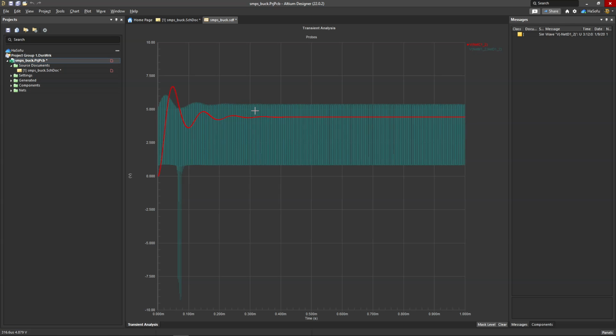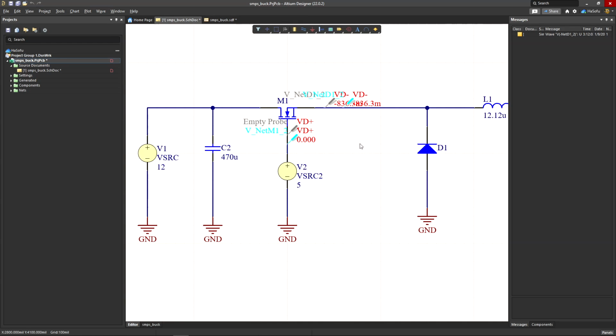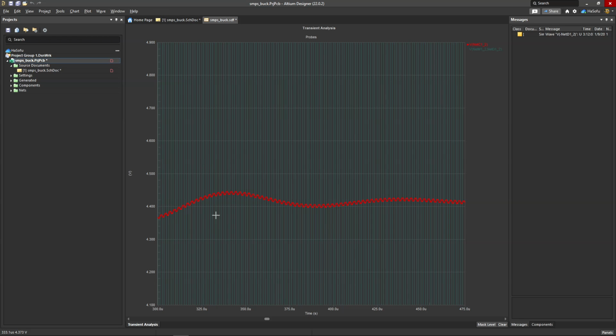And voila, this looks more realistic because it accounts for drops in the devices, maybe the forward diode voltage drop, which if it were accounted for in the duty cycle equation, then we would have gotten something closer to 5 volts. But this is what we are expecting, somewhere in the 4.6 to 5 volt range for the RMS voltage, or the steady state voltage.